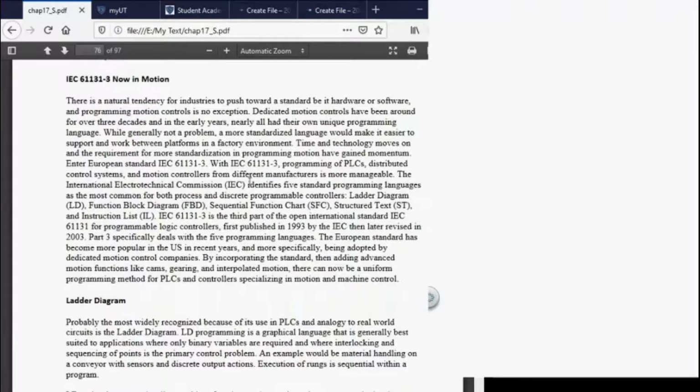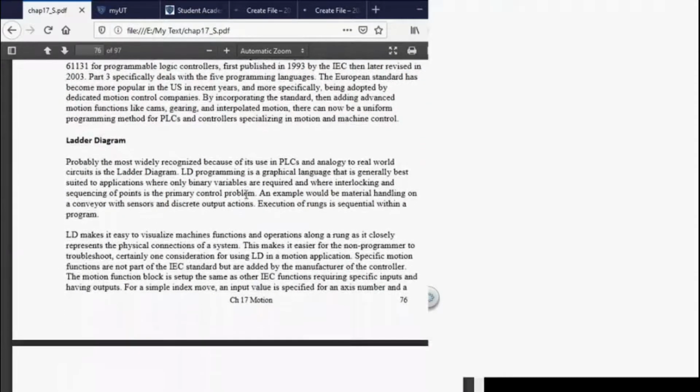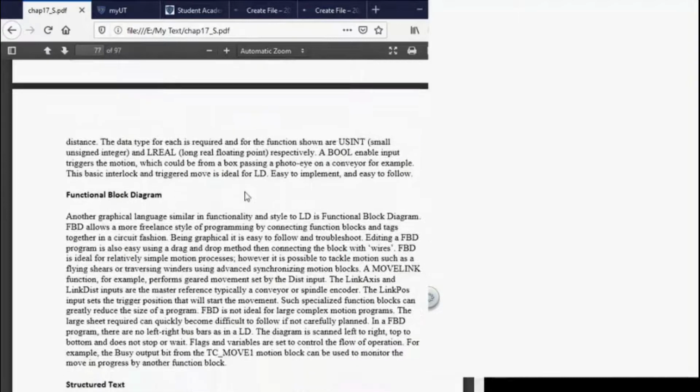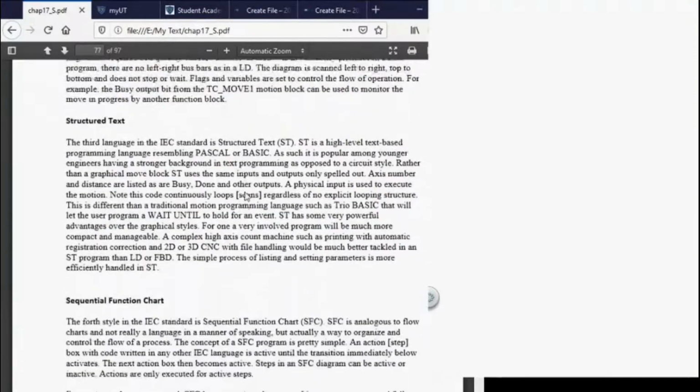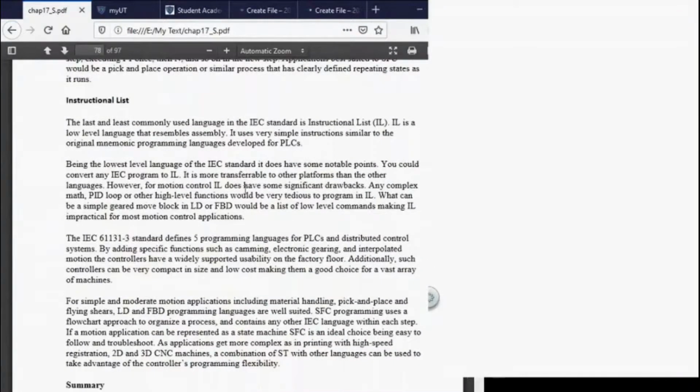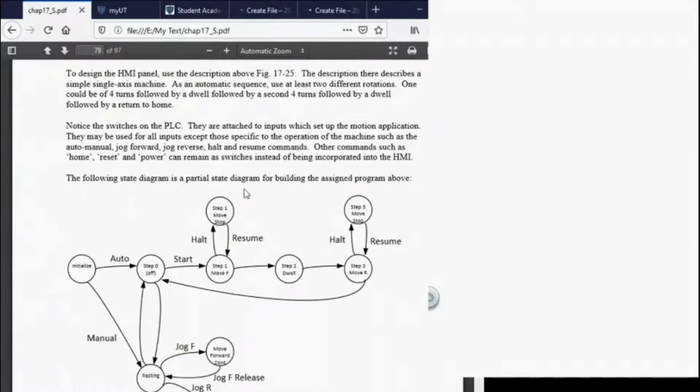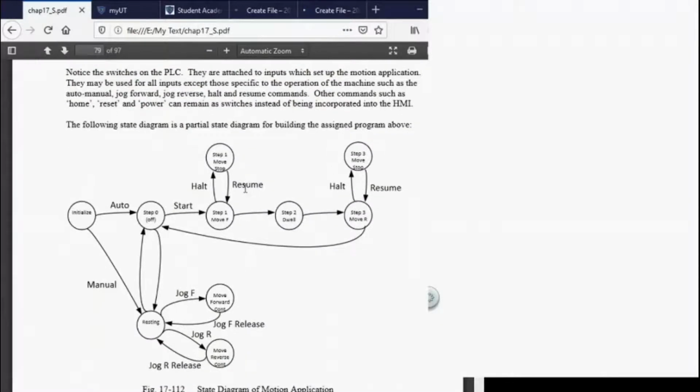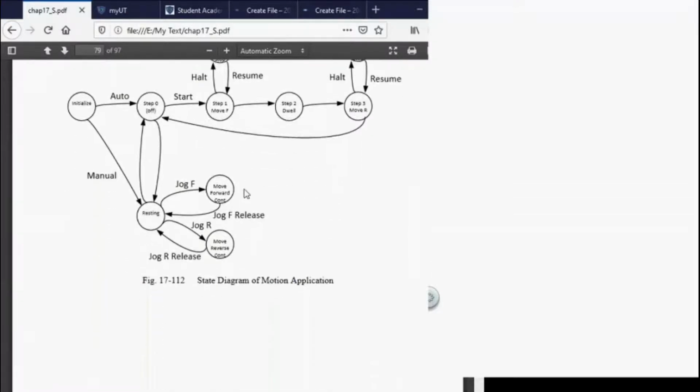And then this would be an article on 61131-3, which would be a PLC standard, and there is movement to incorporate the basic languages of motion with the PLC languages. That said, there are so many of these that it's hard to describe exactly which one's going to win out, but there's an article on that as well. Okay. So that gives you a little bit of an idea about single axis motion, how you would move from single axis to multi-axis motion, and then how you would even go to the more sophisticated M-code and G-code systems.